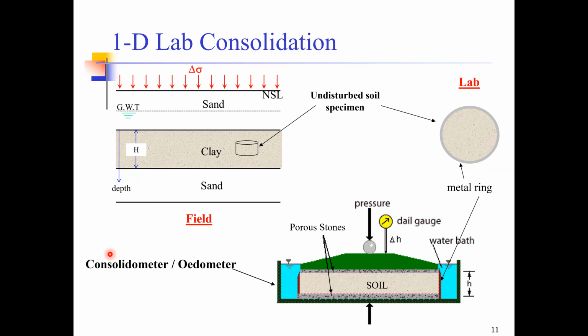Then we put the load on top, and once we apply the load, we monitor the deformation in the soil, because consolidation is a time-dependent phenomenon. It is not going to occur immediately. So we take the readings of this dial gauge at certain time intervals as well.